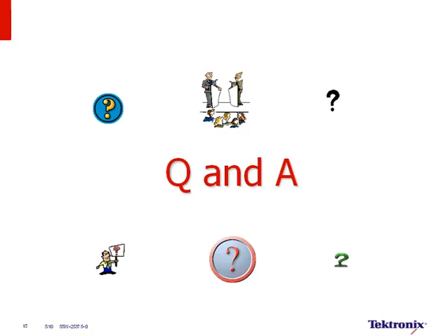So they both achieve the same objective, which is making a BER measurement, but they do it in quite a different way. Okay, so the short answer is there are scopes and scope software that will make a transmitter BER measurement, and there's a BERTScope product that will do a receiver BER measurement.